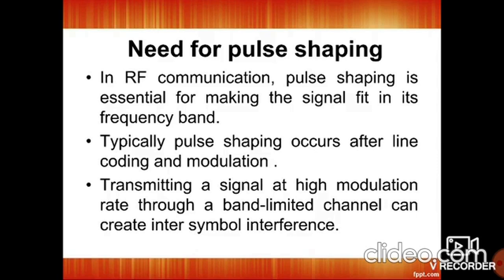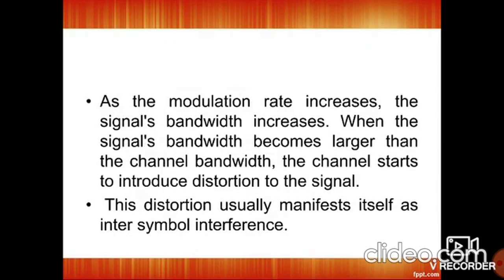Typically, pulse shaping occurs after line coding or modulation. The transmitted signal at high modulation rate is shaped and made to fit in the particular spectrum.